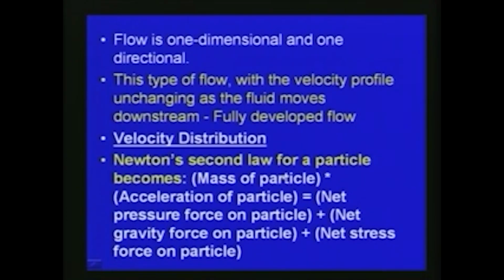By using Newton's second law for a particle in the control volume which we are dealing with, we can write the mass of the particle multiplied by the acceleration of the particle is equal to the net pressure force on the particle plus the net gravity force on the particle plus the net stress force on the particle. So here we use Newton's second law to derive the equation.